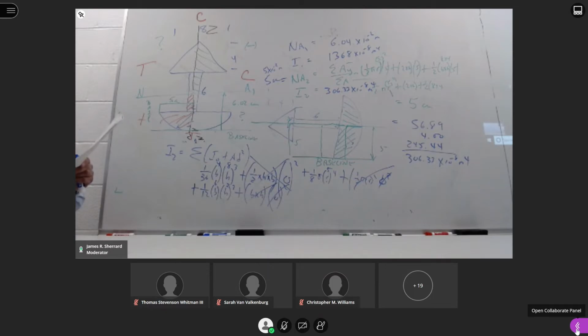If you look at the circle, we're looking at the rectangular moment of inertia, not the one below it, which is the polar moment of inertia. Then the same thing for the semicircle. In this case, they're equal: 1/8 pi r to the 4th.